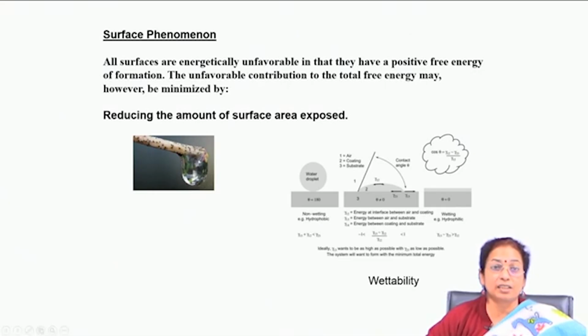So, one important phenomenon related to surface energy is droplet size, and another very important property of the material is wettability, which is again driven by the surface energy. Depending on the surface energy, your wetting behavior will vary. Wettability is measured in terms of the contact angle.